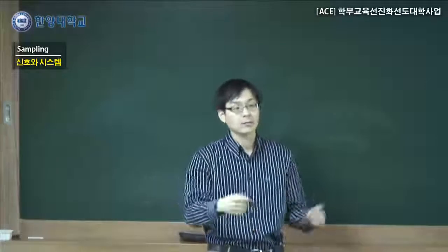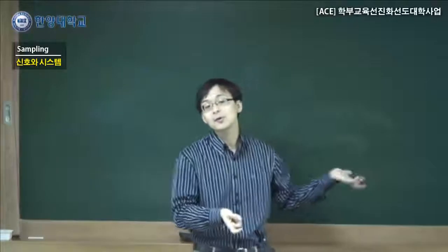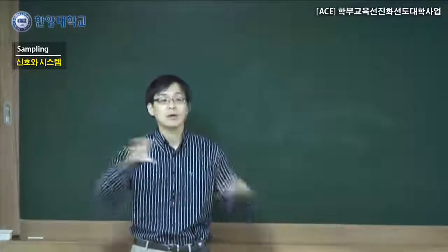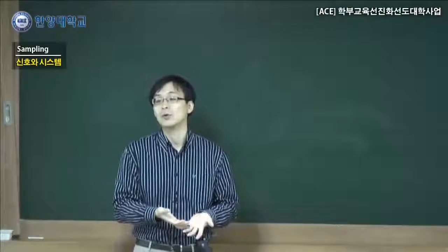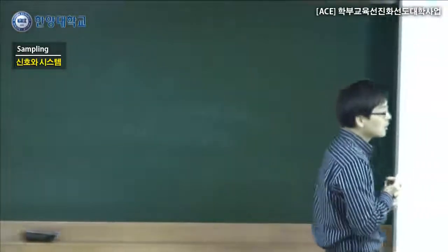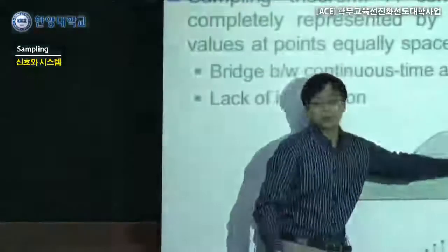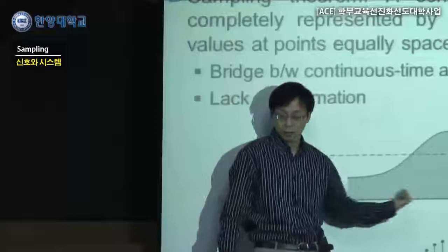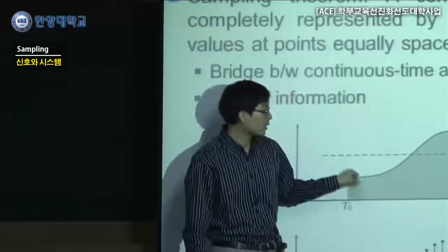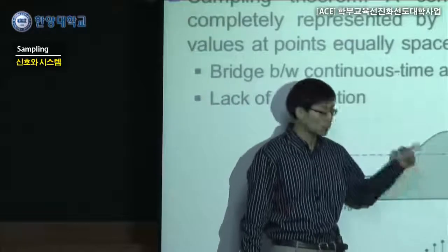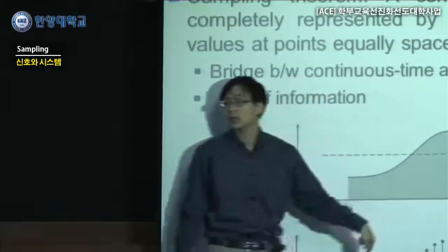They take out some of it and make a sample for you, right? Sampling is similar to that. They pick up a few from a large portion. That's why we remember the word sample. So you can think in a similar way. This large portion is actually an almost infinite number of values on the y-axis. We pick up a few of them. Discrete time signal. That's sampling.